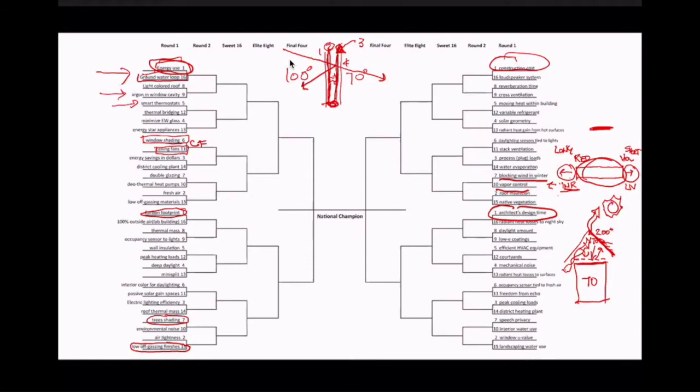And actually, for this place in the attic, there's a product that I think I included in the Amber book, but it's little pieces of foil that you blow in. The idea is you can have the reflection, but still allow moisture to pass through so it never gets trapped.